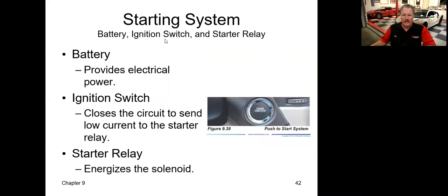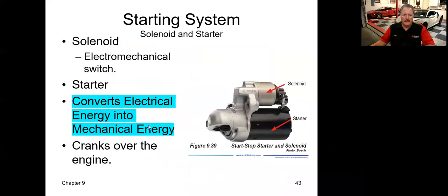Starting system: battery, ignition switch, and starter relay. That's part of the starting system. Solenoid sits on top of the starter here. The starter converts electrical energy into mechanical energy, okay, and cranks over the engine. That's what it does.